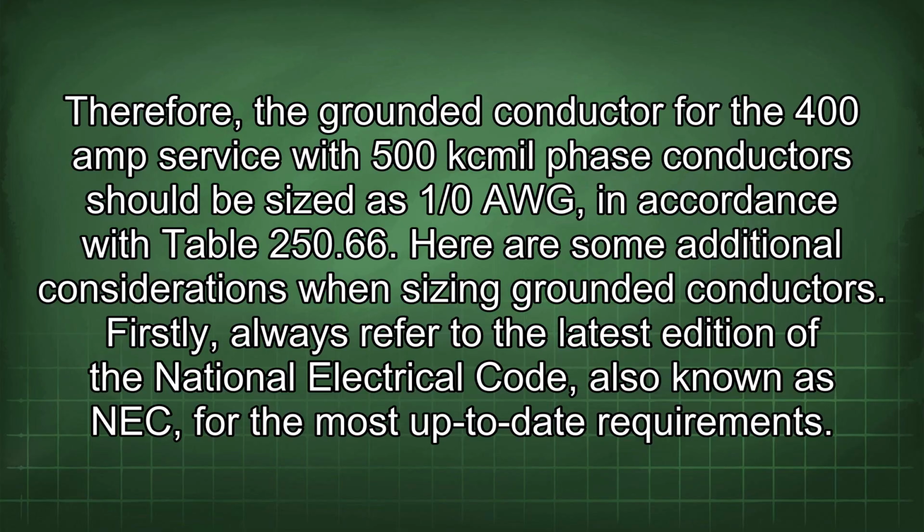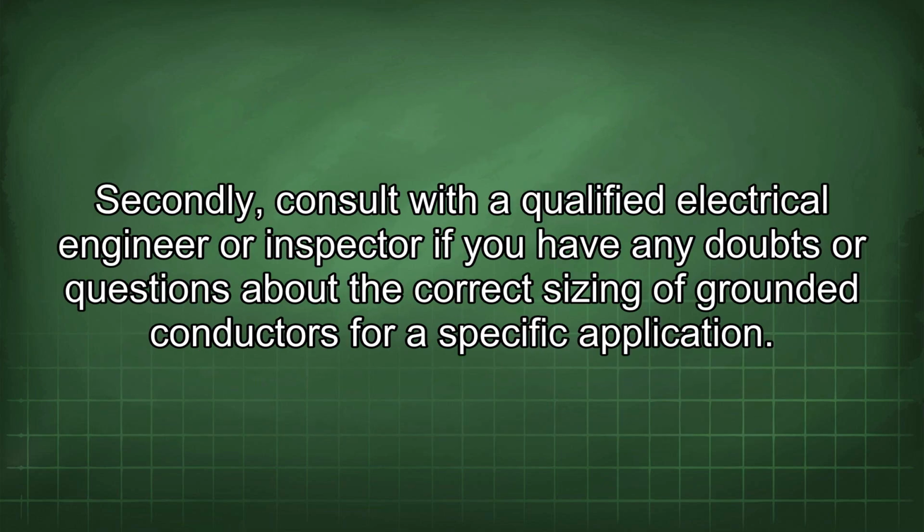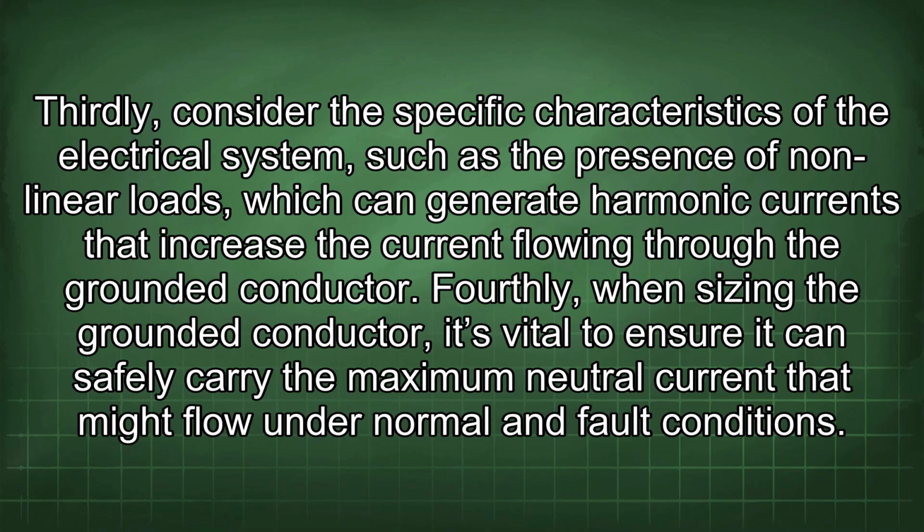Here are some additional considerations when sizing grounded conductors. Firstly, always refer to the latest edition of the National Electrical Code, also known as NEC, for the most up-to-date requirement. Secondly, consult with a qualified electrical engineer or inspector if you have any doubts or questions about the correct sizing of grounded conductors for a specific application. Thirdly, consider the specific characteristics of the electrical system, such as the presence of nonlinear loads, which can generate harmonic currents that increase the current flowing through the grounded conductor.